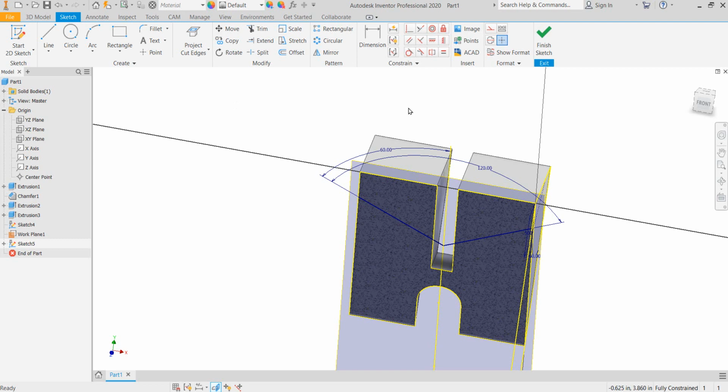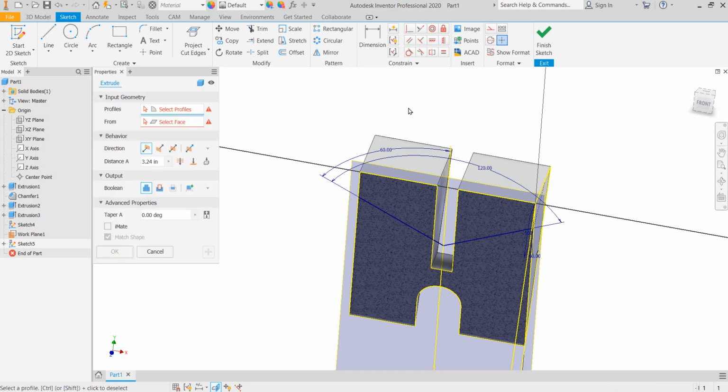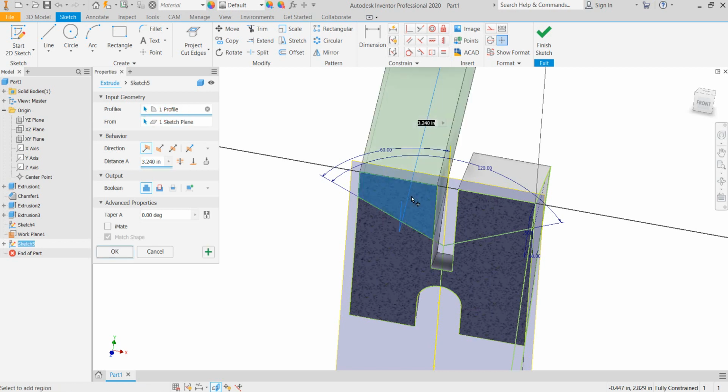All right, and so now we'll go extrude. And I want to choose that trapezoid, I guess. I don't know. If you did the cut planes, you just click twice and select them both. If you projected those surfaces, you'll have to click one for the upper portion and once for the lower portion.